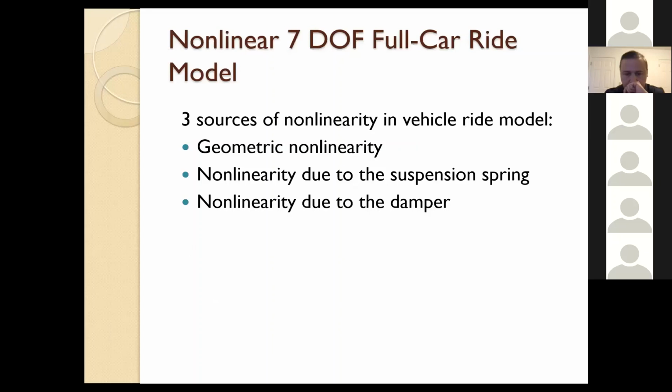Modeling of cars, actually there are two ways to model cars. One way is a detailed model, which people will use finite element for. Of course, this is one of the most complete modeling, but at the same time, it has many drawbacks. It will need a lot of computational facilities and a lot of computational time, and it will need good expertise to look into the result, because if you are not expert in finite element, you don't understand the tricks behind meshing and selection of elements and many of these things, the result might be deceiving and might not be correct.